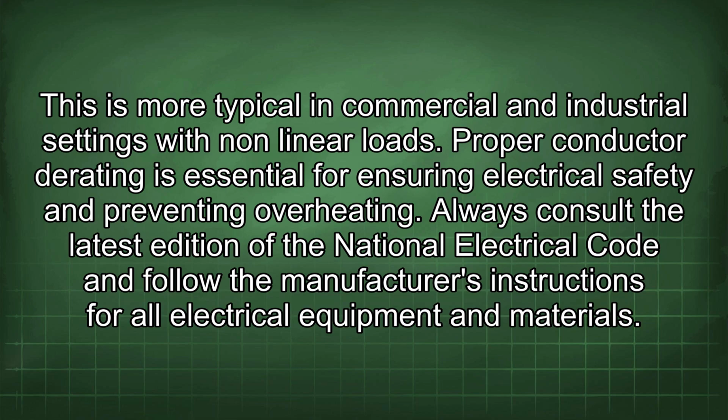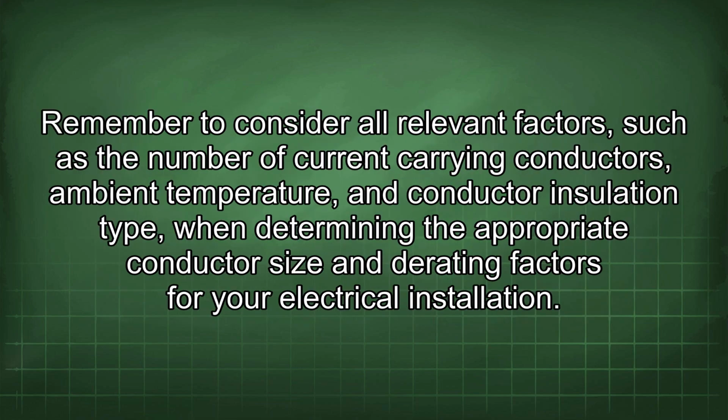Proper conductor derating is essential for ensuring electrical safety and preventing overheating. Always consult the latest edition of the National Electrical Code and follow the manufacturer's instructions for all electrical equipment and materials. Remember to consider all relevant factors such as the number of current-carrying conductors, ambient temperature, and conductor insulation type when determining the appropriate conductor size and derating factors for your electrical installation.